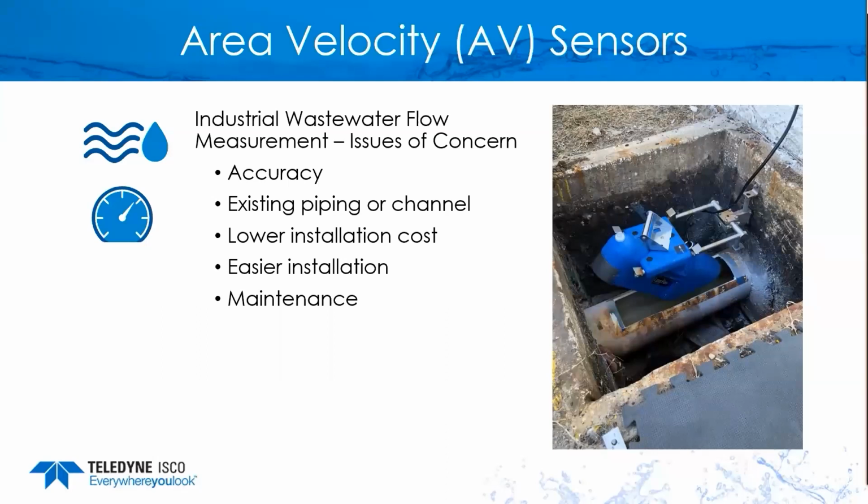And then other considerations are the maintenance. Do you have a lot of debris going through there? So you may want to consider using a non-contact sensor to read your flow rates.